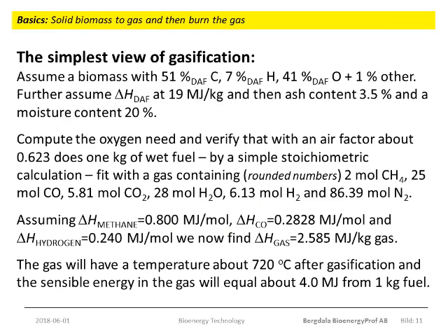Let us now look at a case where the solid biomass is first converted to a gas and what happens then. What you do when you first convert a fuel into another fuel and then finally burn the converted fuel is that you split the combustion process in two. So let us do a very simplified example where we assume a fuel analysis and then just use simple stoichiometry to alter the state of the fuel from one assumed solid into an assumed gas. You will see the basics in the slide.